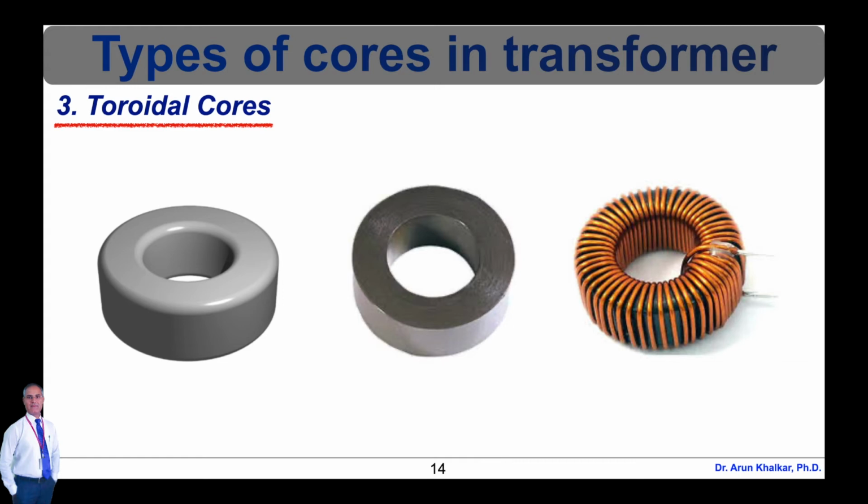The symmetry of this geometry creates a magnetic field of circular loops inside the core, and the lack of sharp bends will constrain virtually all of the field to the core material. This not only makes a highly efficient transformer, but also reduces the electromagnetic interference radiated by the coil.